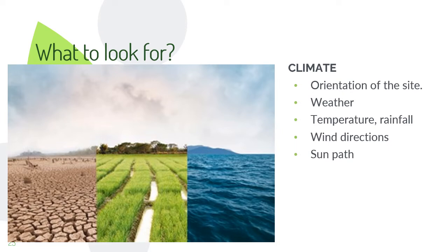Take some time to walk around the site as much as possible. Take note of the general topography of the site and any significant changes in level. Also note any indications of what is underneath the surface. For example, any marsh grasses could suggest that there is a high water table. If the soil is sticky, it could indicate the subsoil on the site is clay.